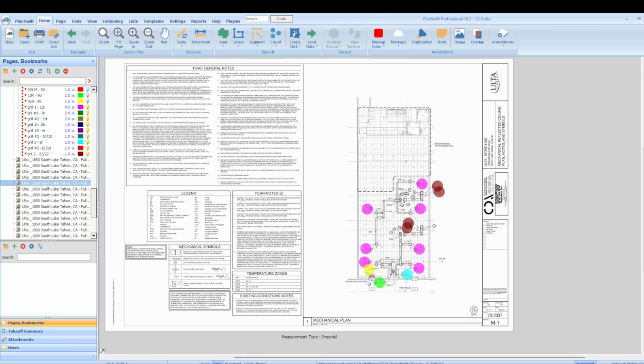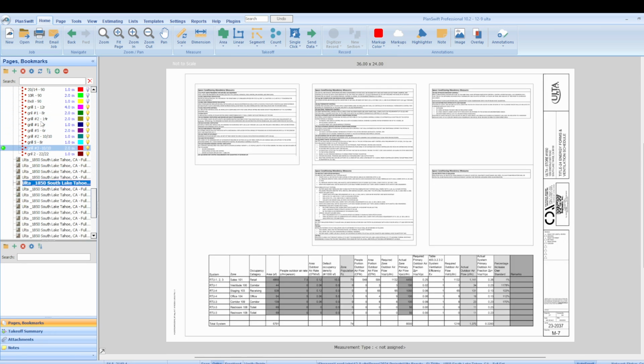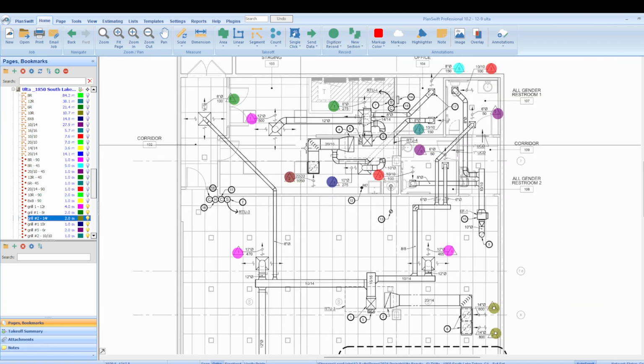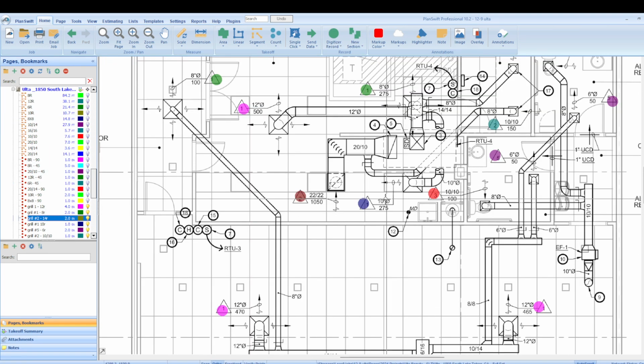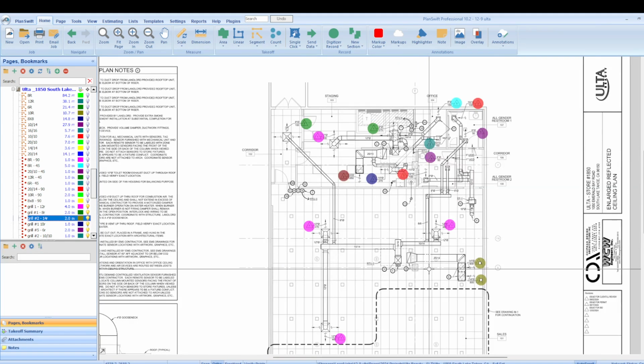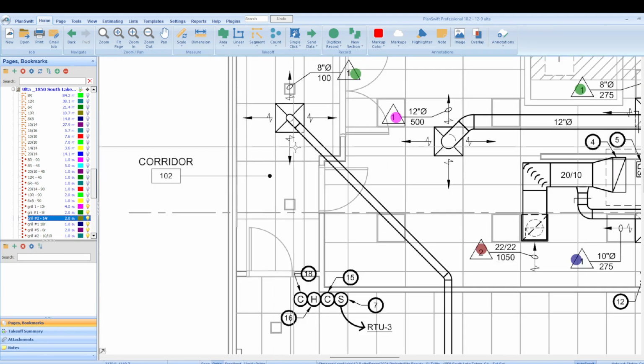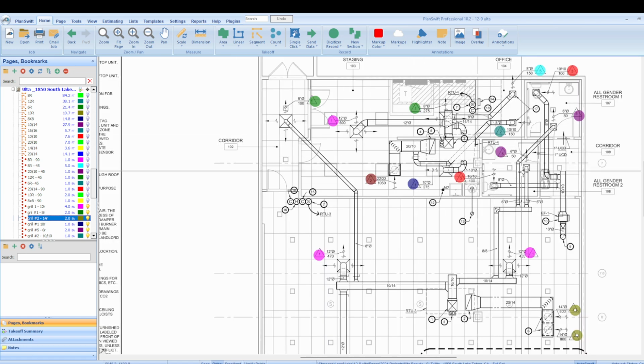And it's important to know all of those symbols too, because if you are the HVAC person, you probably are going to need to look at the reflective ceiling plan to see how these are your supply grills in the ceiling. If there's a question about any error in any of the sets of plans, you should be able to look through it and determine if it makes sense.